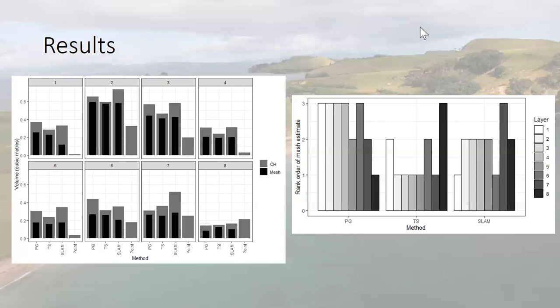And I am interpreting that as basically because photogrammetry is accounting for more variation within the surface, concavities, and convexities. It's just accounting for more variation, and so you get a higher volume. SLAM is roughly similar, but as I said, there were difficulties in calculating their volumes. That's probably where that's coming in. And then total station is more of your clean, idealized exterior of the trench, what that maximum excavation area is.